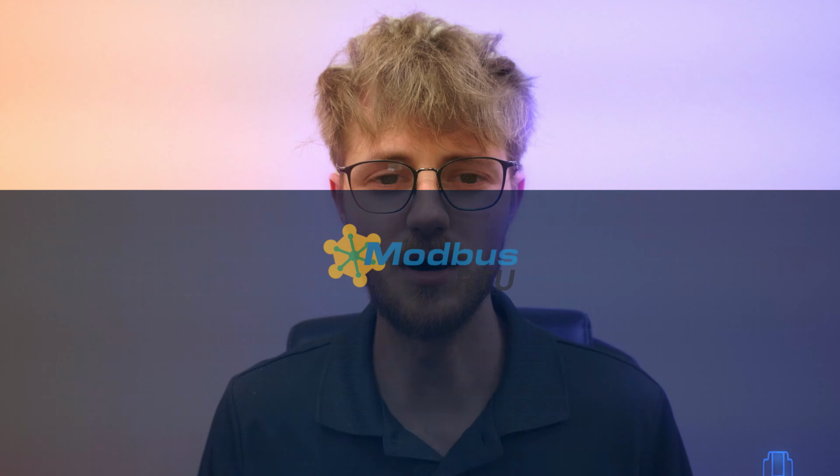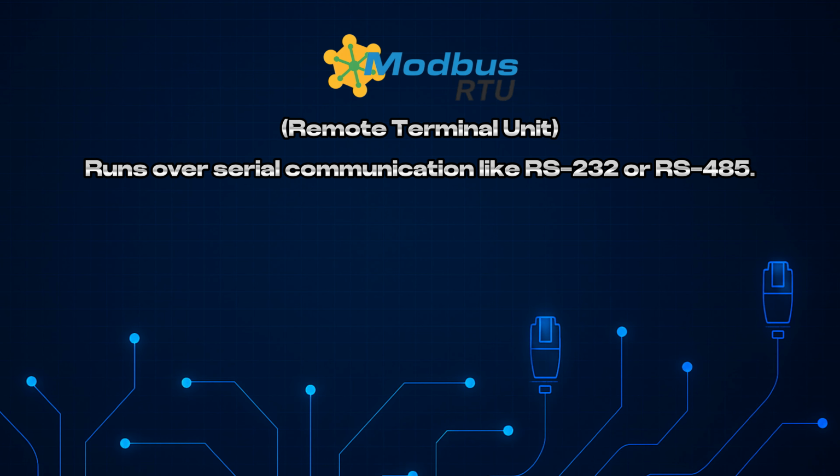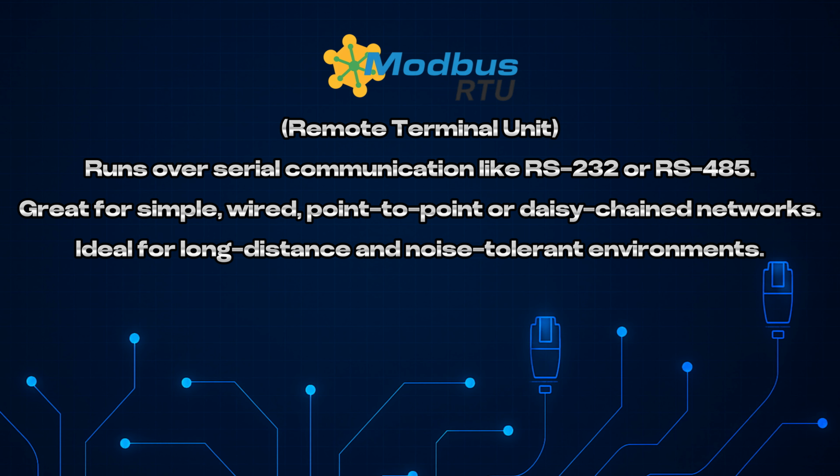Now let's talk about the 2 major versions of the protocol. Modbus RTU, or Remote Terminal Unit, runs over serial communication like RS-232 or RS-485. It's great for simple, wired, point-to-point or daisy-chain networks, and it's ideal for long-distance and noise-tolerant environments.